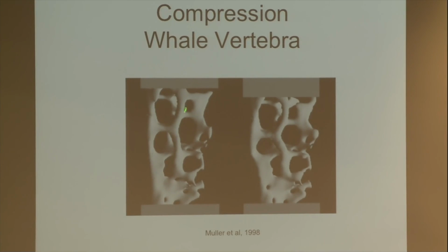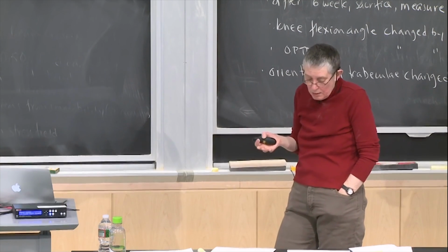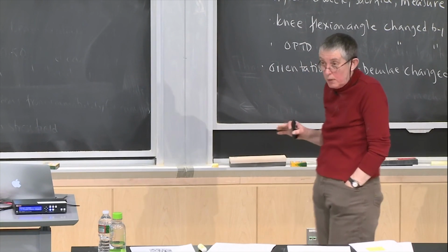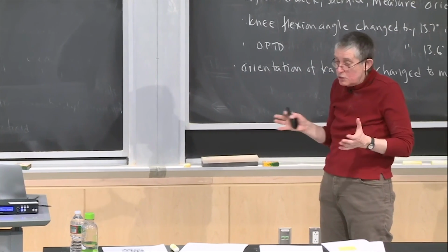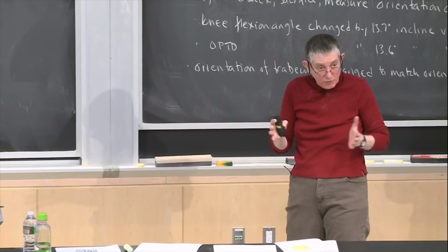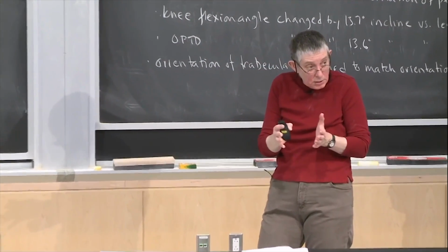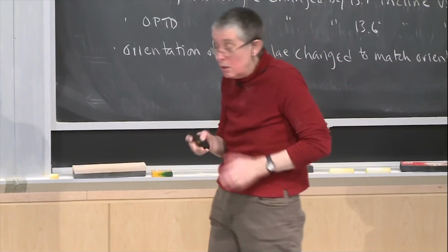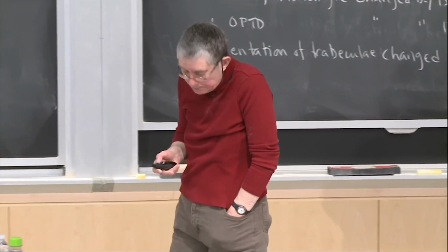And if you look at this sort of column here, this trabecula here, you can see it's kind of bent out and bowed out more. And people have found that usually the linear elastic behavior is controlled by bending of the trabeculae, and the plateau stress is usually controlled by some sort of buckling, but it's not elastic buckling. You don't recover it. If you take a piece of bone and you compress it, it's going to have a permanent deformation. So it's inelastic buckling.